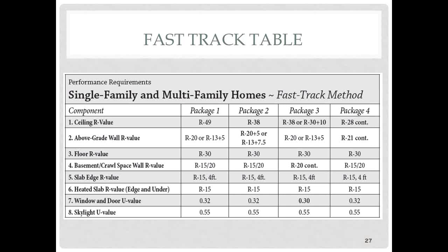Similarly, there's slab edge R values. There are additional slab insulation requirements for heated slabs, radiant slabs. The window and door U values are given there, and the skylight U value, and that's all package 1.